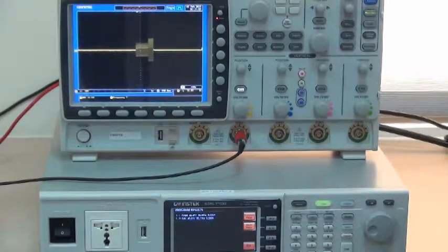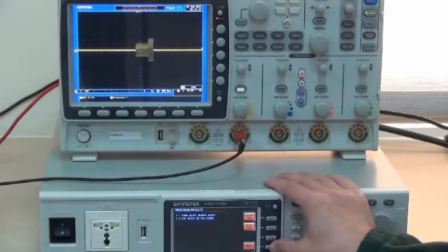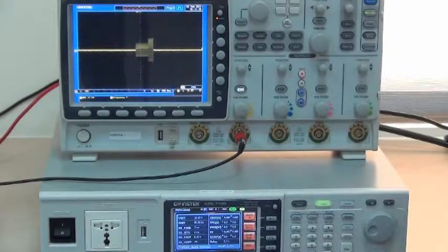That means the ceiling and floor setting range are incorrect. From the oscilloscope, we observe APS-7000 only executes to the failed step. Now press F4 Exit to finish. The above example is from setting different voltage output for 3 sets of steps. DUT's current spec ranges are set, and whether it surpasses the spec is determined.